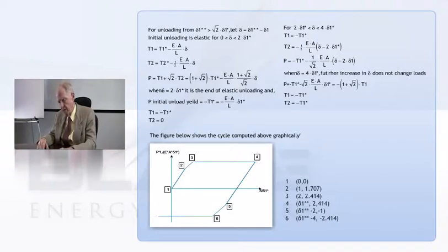When you think about it and look at it, you can ask yourself the question, well, suppose I take the usual steel tension bar, polycrystalline material and all that, and you pull on it and push on it. You get this so-called Bauschinger effect. And how does that Bauschinger effect compare to Massing's hypothesis? Massing's hypothesis exaggerates, well, it comes down farther than the actual load would come.